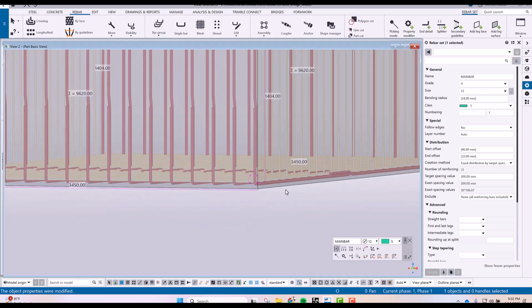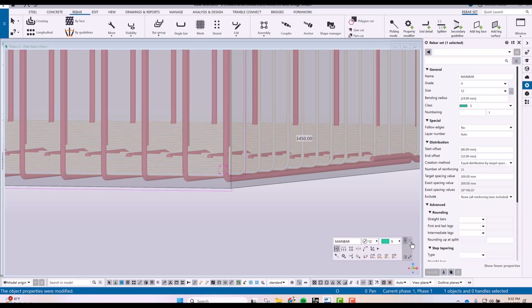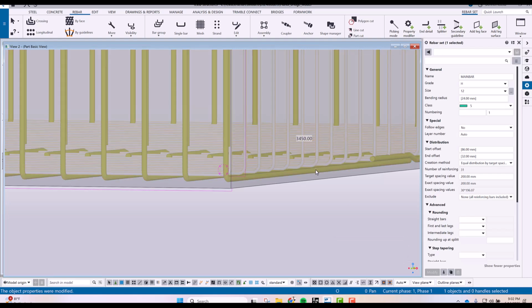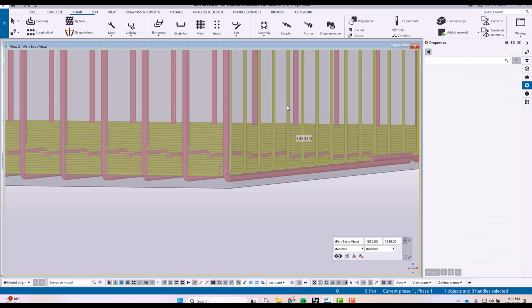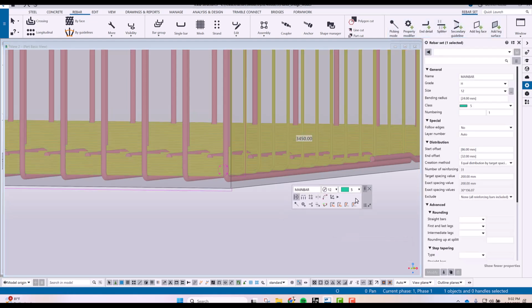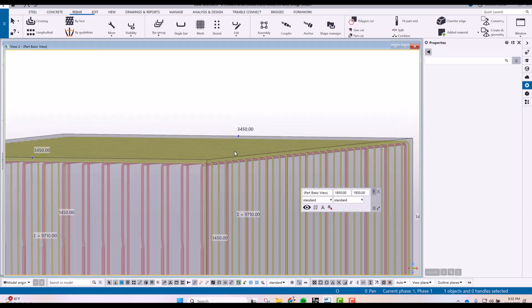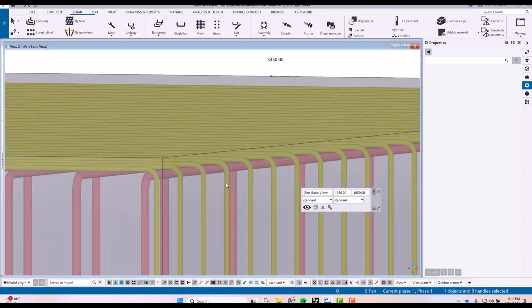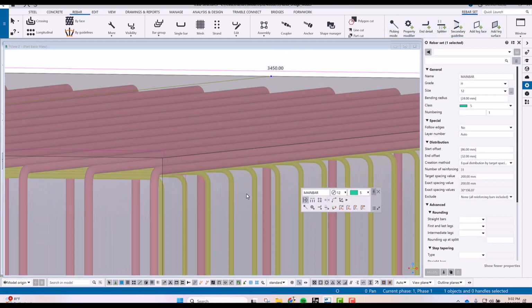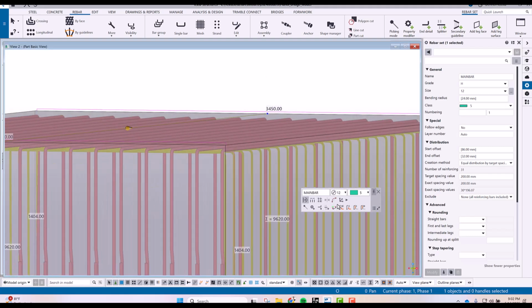It's very simple because all you have to do is select the rebar and then open the contextual toolbar. So here there is a contextual toolbar. So just simply select this move outermost layer. So it will change the position top and bottom. So again, if I select the inner layer, it will change automatically.